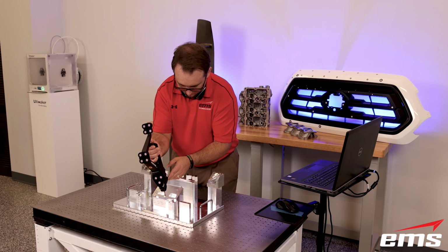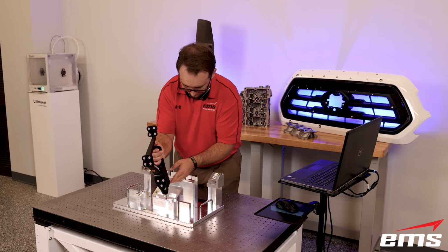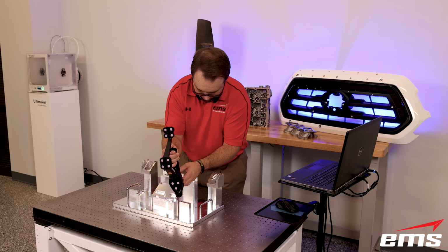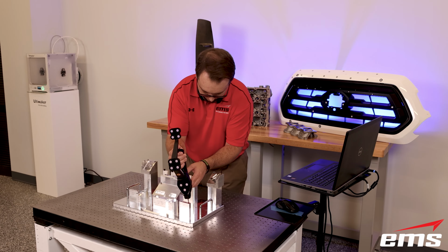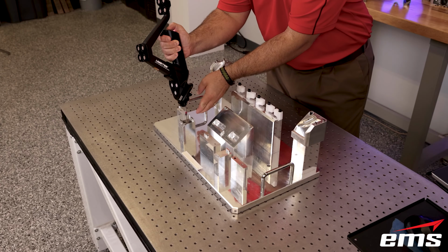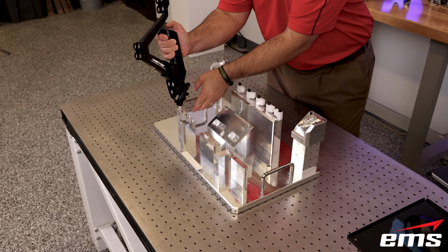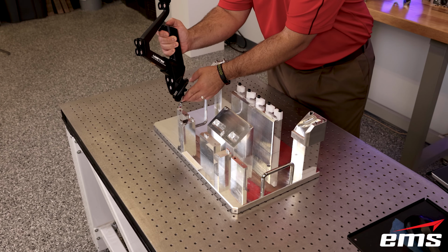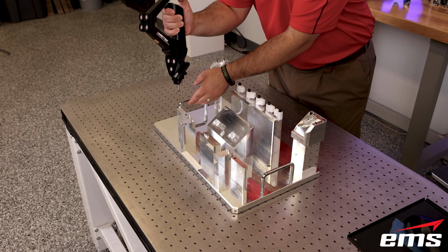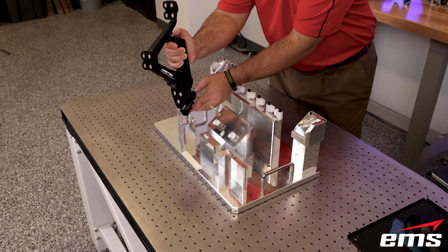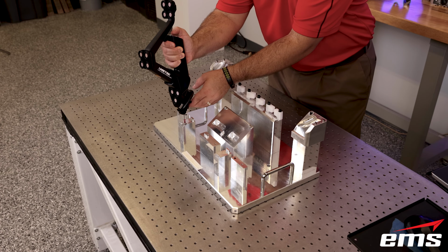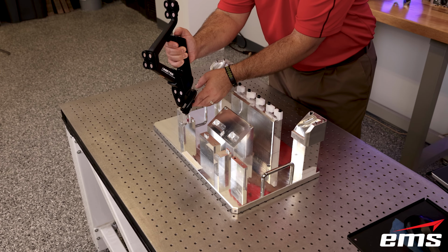Like we did before, we will use probing to qualify the fixture, basically going around and measuring the fixture at key nesting and hole locations and making sure our fixture is correct before we start inspecting parts. Because if your fixture isn't right, there's no way to guarantee that your parts are right. So the first step is always qualifying that fixture and making sure it was built right. And probing is very quick and easy for this qualification process.